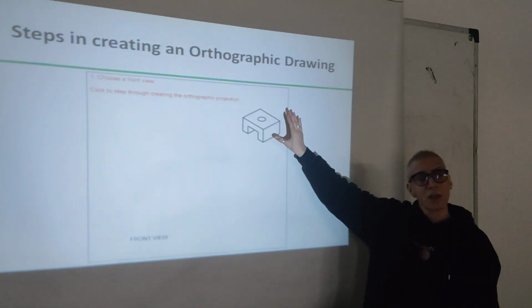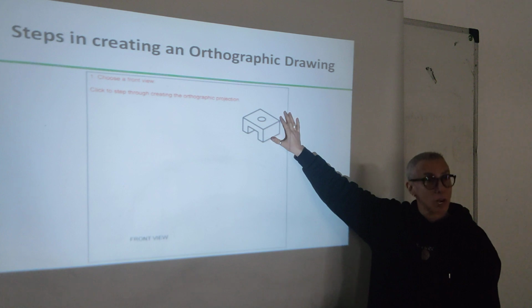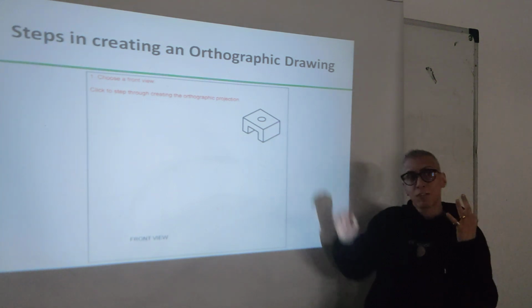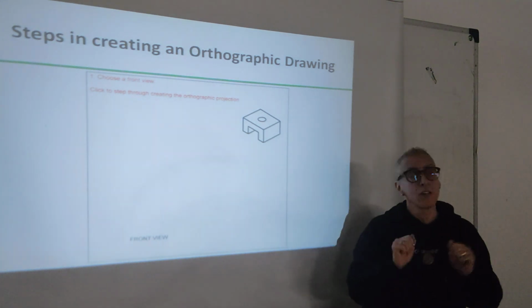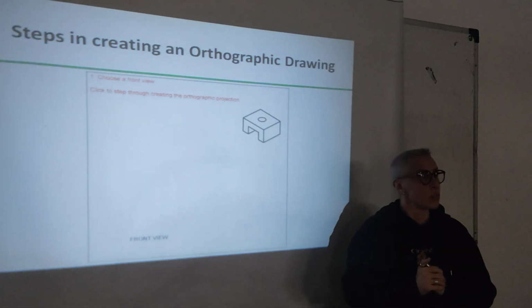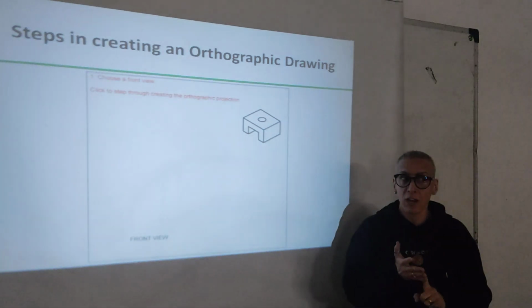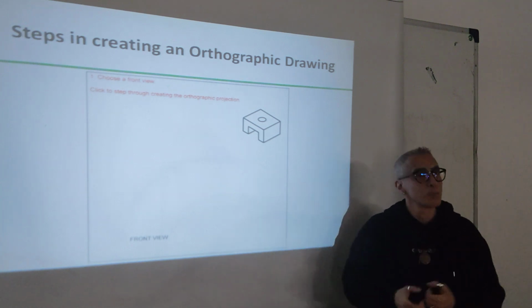And there are measurements on this object. For example, I tell you, draw this in orthographic multi-view drawing, 3 views. As I explained last class, sometimes you use 6 views and sometimes 3. In these drawings, we will use 3 views: the front view, right side view, and top view. Because we don't need more. They are very simple objects.